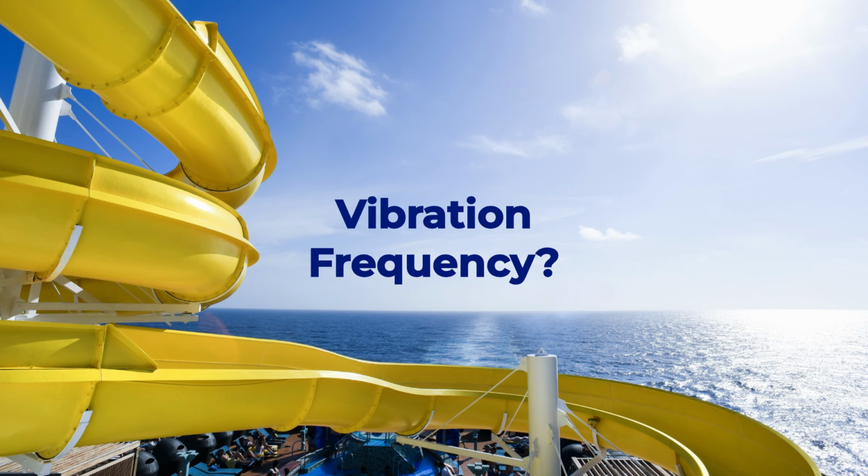So as the flow is hitting the shedder bar, it's shearing off, it's alternating back and forth. If you stood on a bridge and you watch the water go past you and you have the pylons there and the bridge, you see a swirl. If it's hitting it perfectly, you'll see an alternating swirl back and forth.